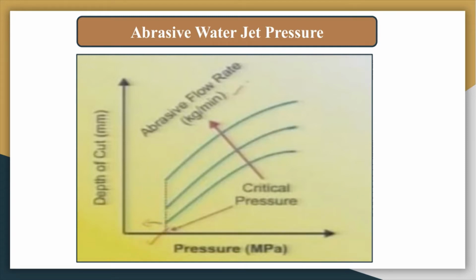And as the pressure increases, the depth of cut also increases, but beyond a certain pressure this is not a linear relation. It is a non-linear relationship, and it tries to stabilize beyond a certain pressure.